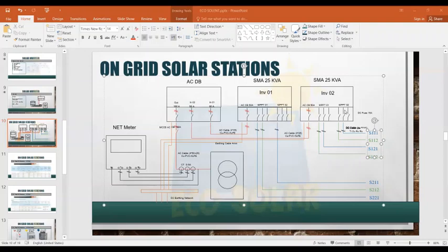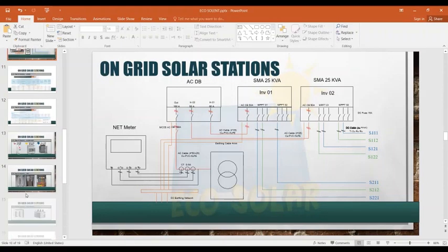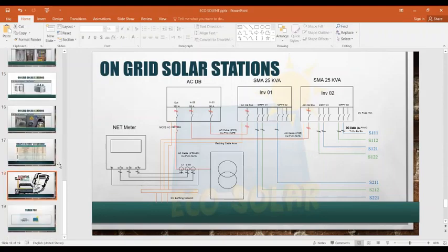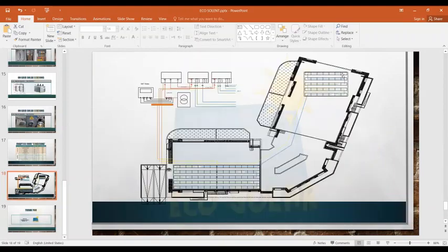And here are the colors on the right, S11, S12. All these cables are coming from the solar panels. These are the symbols. The first string is colored blue, the second one is colored green, and so on, to distinguish the cables by color. These are the DC strings actually attached to the solar station. This is the first string, second one, third one, and so on.